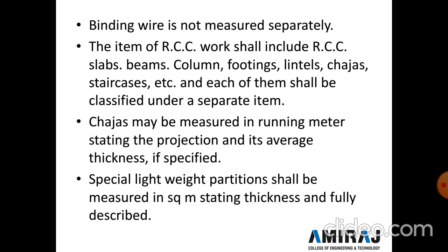The item of RCC work shall include the RCC slab, beam, column, footing, lintel, chhaja, staircase, etc. Each of them shall be classified under a separate item, because different formwork is required, different strength is required, and a different quantity of concrete is required, so every item is counted as a separate item.